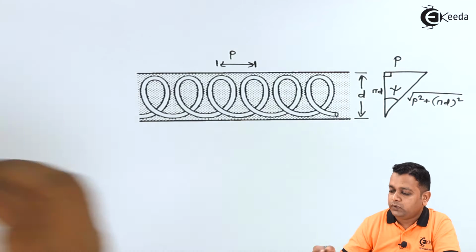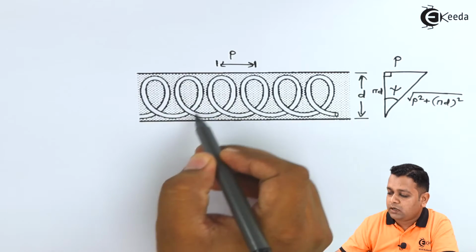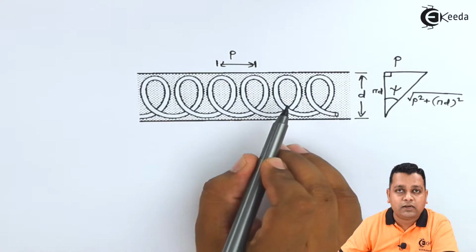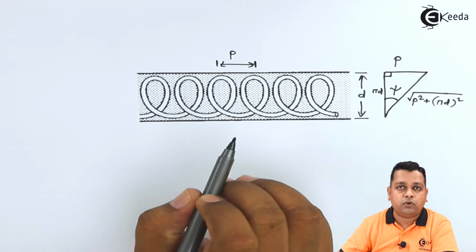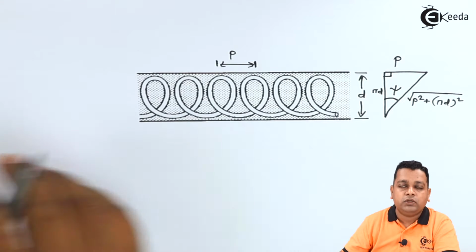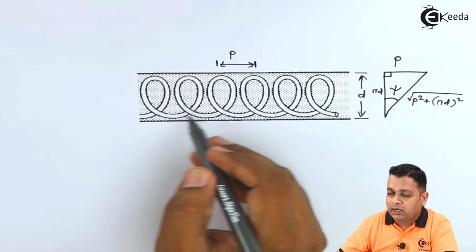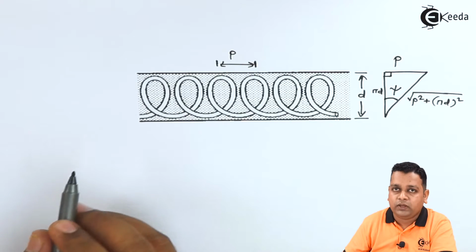We want the signal propagating through this helix and the electron beam, which has the axial direction, to have more and more interaction with each other. So here we can have one mathematical ratio with respect to the phase velocities of the signal propagating through the helix and the other.